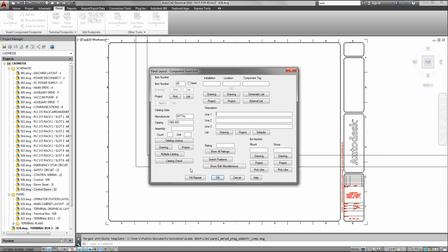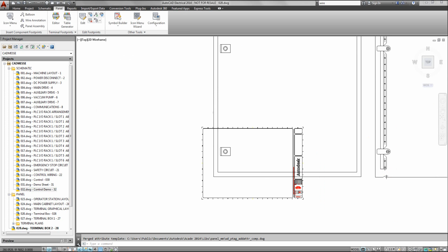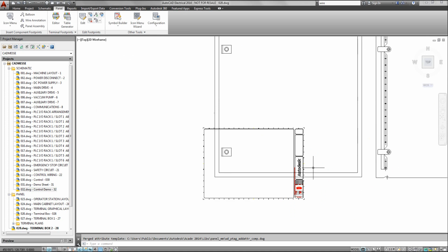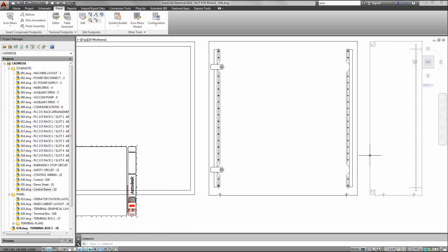Now, because in AutoCAD, like all AutoCADs, the scaling is always in real life as far as the components you're dropping in go. Obviously, my drawing is only an A4 size in reality. So what I need to do is actually scale my drawing to suit. I'm just going to get rid of that view on the end as well. I'm not going to use that.